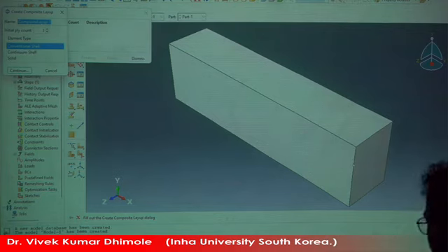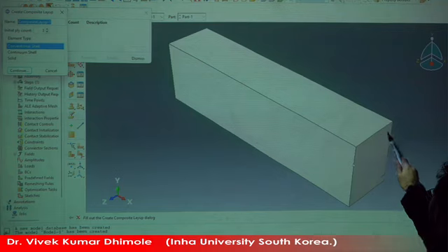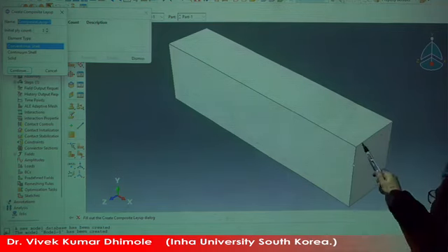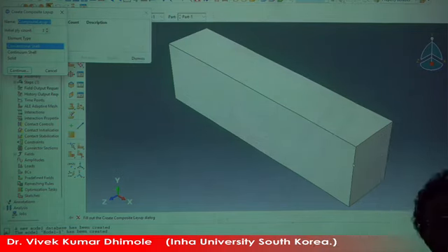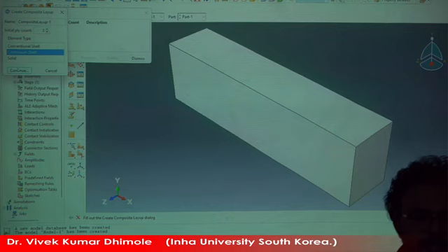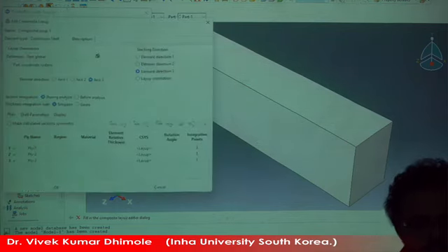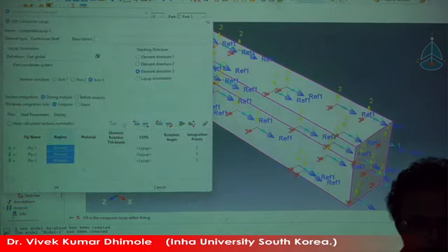And the ply means, suppose I define 3 plies and this is 10 mm, so 3.3, 3.3, 3.3, 3 plies will be decided. Suppose I decide 5 plies, so 2, 2, 2, 2, 2, each ply will be cut out, getting the point? So we can see the ply stack layup later on. So now I just create the 3 plies, continue, and let's decide the region, all the same, done.